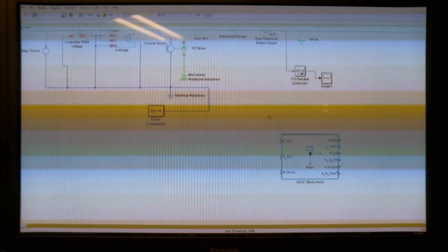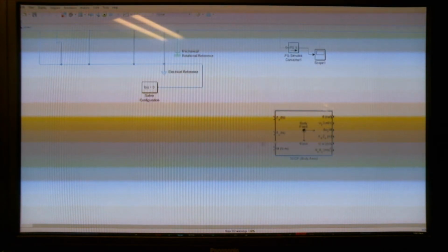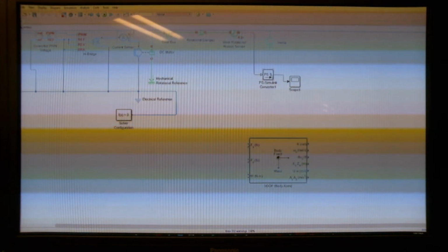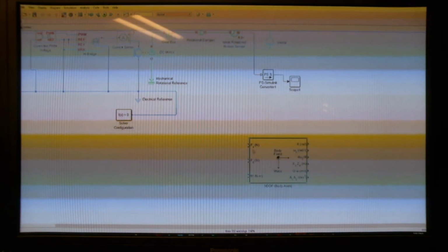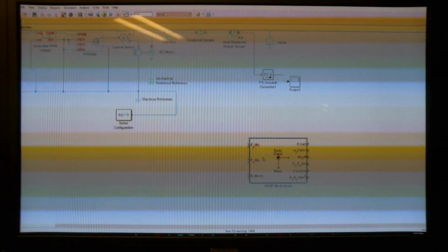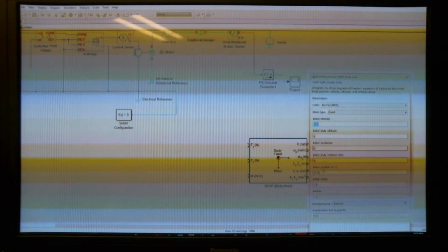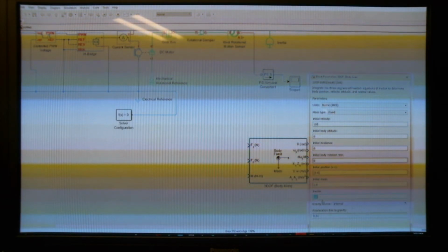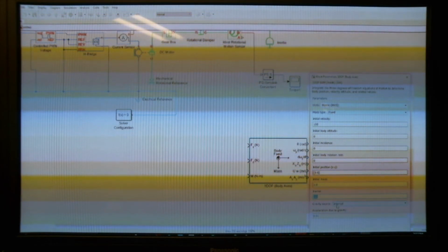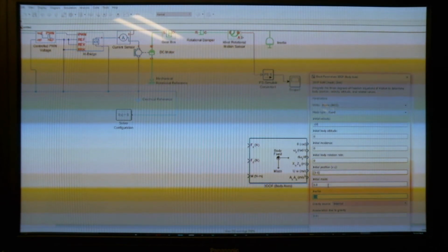But here's the thing: you can't just connect these blocks to this block. You have to connect the output of a Simulink block to this, and it'll do the I alpha thing for you. You'll give your initial velocity, your initial position, your mass, and here's the thing: it won't actually give you inertia. So you won't put in an inertia tensor for 3DOF.